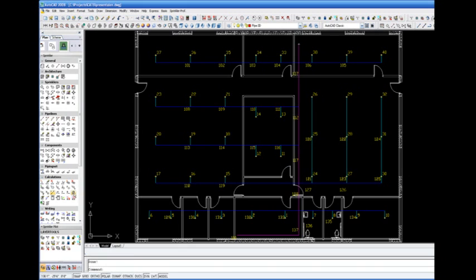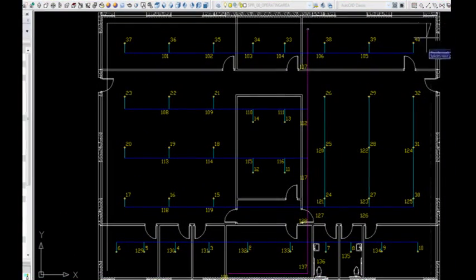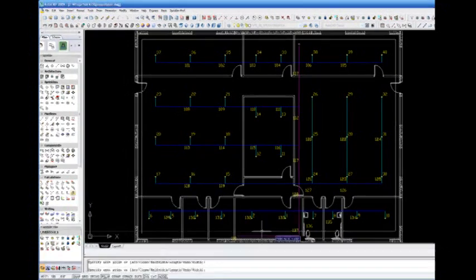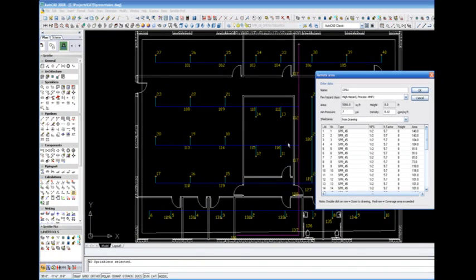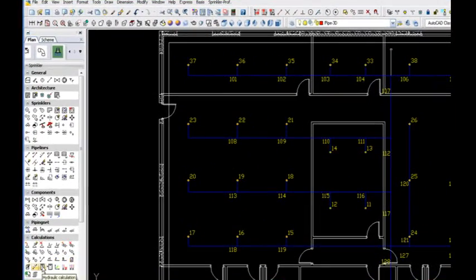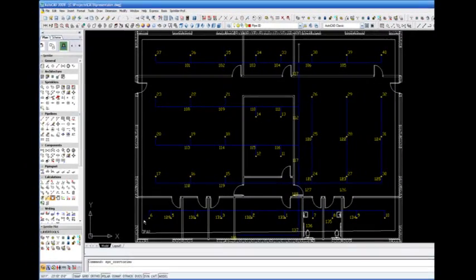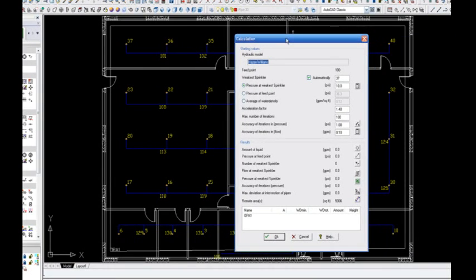Next, you define the operating remote area for the hydraulic calculation. The interconnecting pipe sections are numbered automatically. Prior to the hydraulic calculation, you have to recheck the starting values. You can modify or select the starting values indicated.